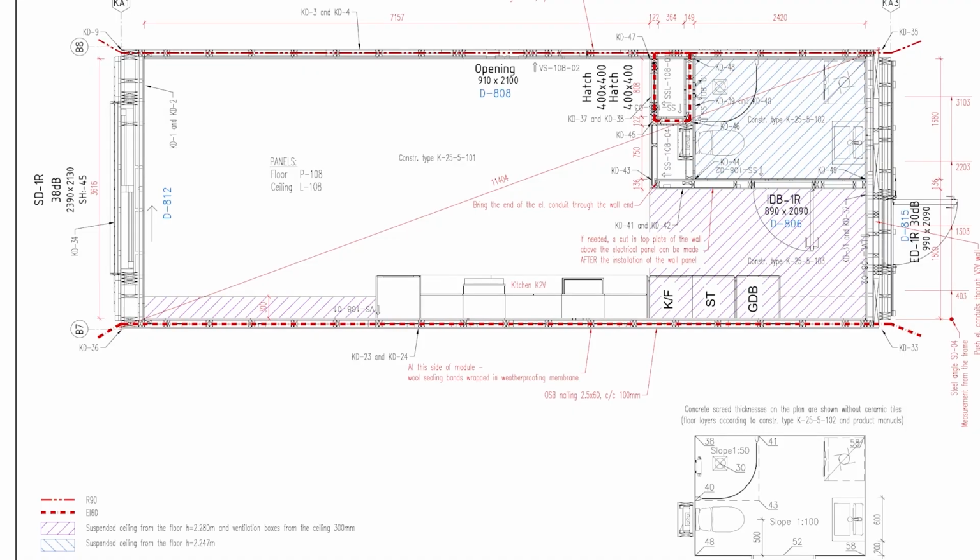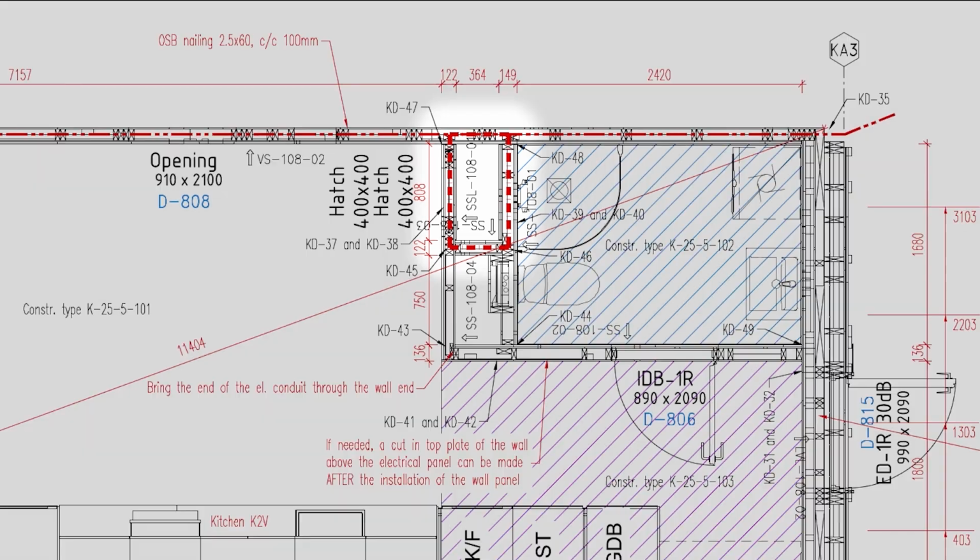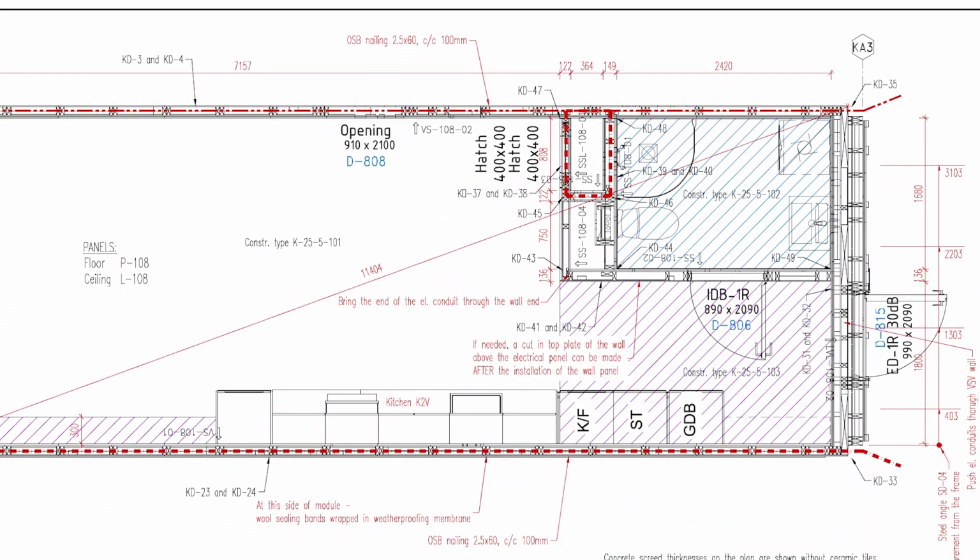If there are openings in the floor panel, such as a stairway or a shaft opening or both, the locations of the openings must also be checked either in relation to the walls or to the axes shown in the drawing. If it is intended that water pipes or electrical conduit pipes will go into the walls from the floor panel, then their position relative to the marking lines must also be checked.